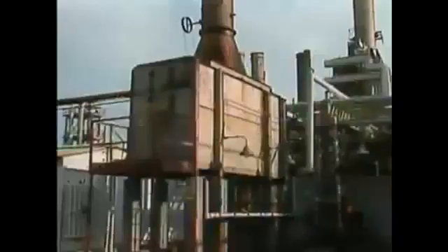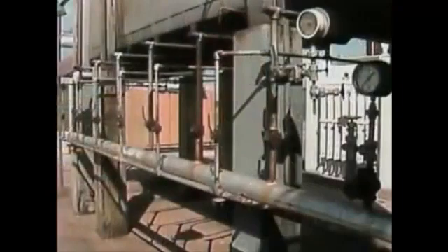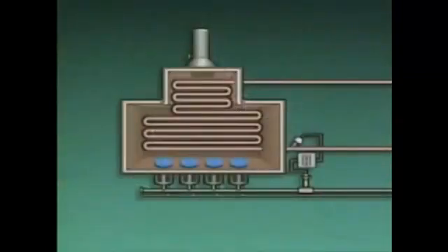In this part, we'll look at furnace fuel system problems. Fuel problems can arise when the flow of process fluid is significantly reduced and it's necessary to operate the furnace at a lower firing rate. At a reduced firing rate, it may be hard to supply enough fuel to the header to keep all the burners going. To avoid this, the operators may close off some of the burners and their registers so that no fuel is sent to them. When you shut off fuel to some of the burners, the fuel flow to the operating burners will be increased, reducing the risk of flameouts. Firing with fewer burners is a way of maintaining fuel pressure while satisfying the reduced demand.